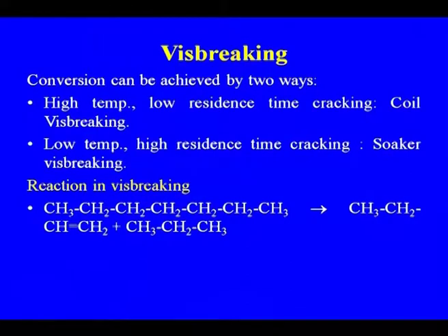These are the reactions that are taking place in case of Visbreaking. The reactions in the cracking process, I told you, are very complex in nature, and depending upon the operating conditions, temperature, pressure, and type of feedstock, the product which you are getting after the Visbreaking will vary.